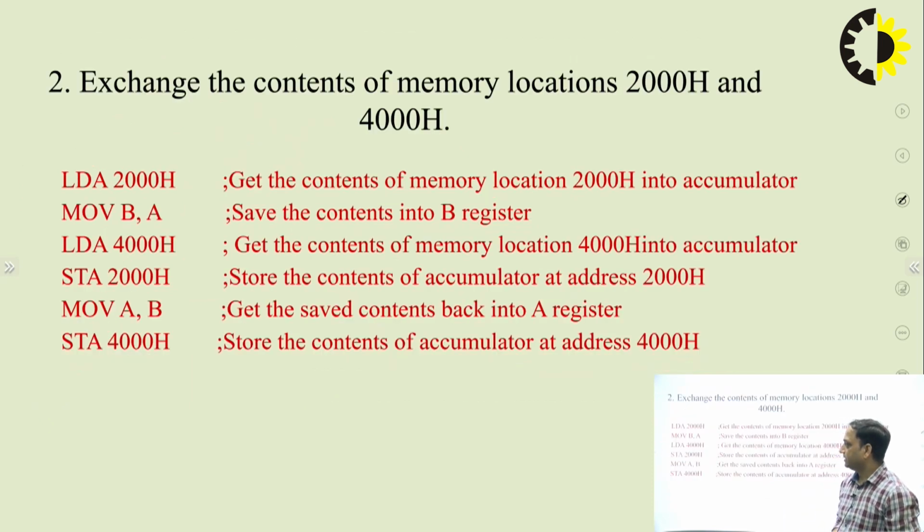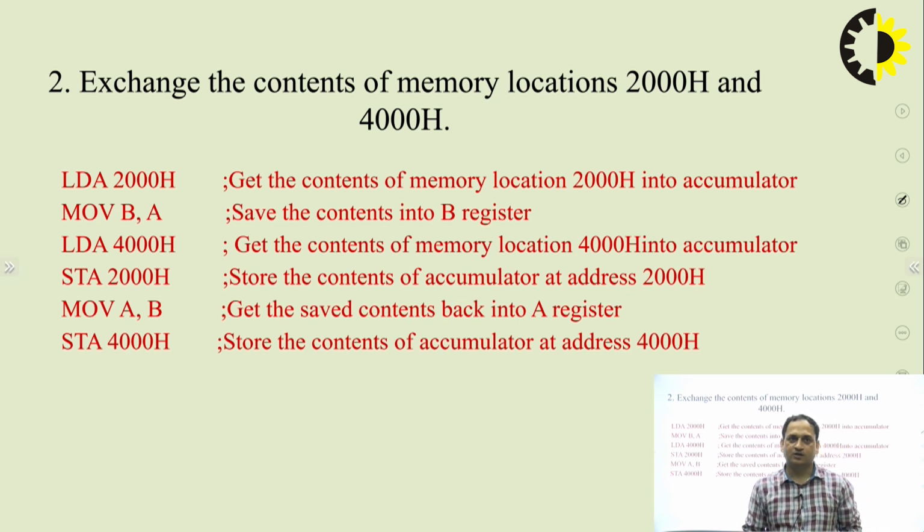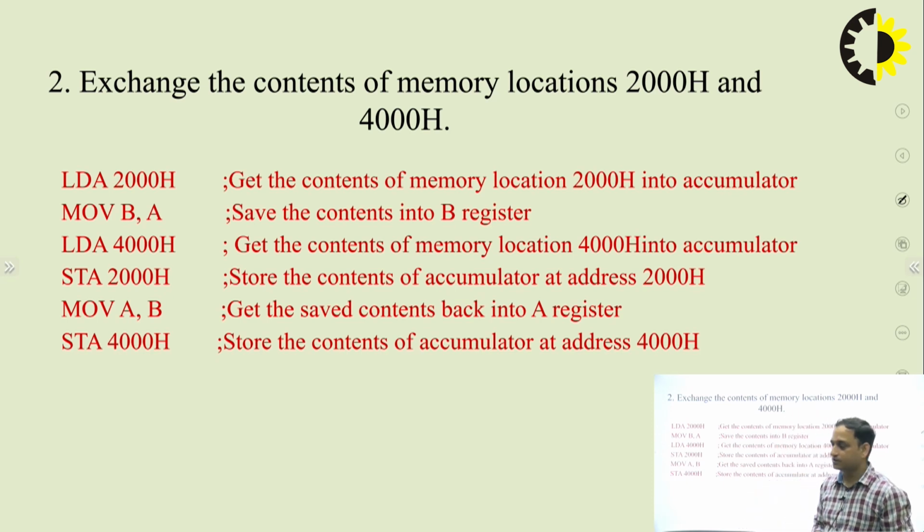Then we have the next program, that is to exchange the contents of memory locations 2000H and 4000H. We have to just exchange the contents of those memory locations. For this we can start with LDA. As we said in the previous case, this is the opposite of STA.